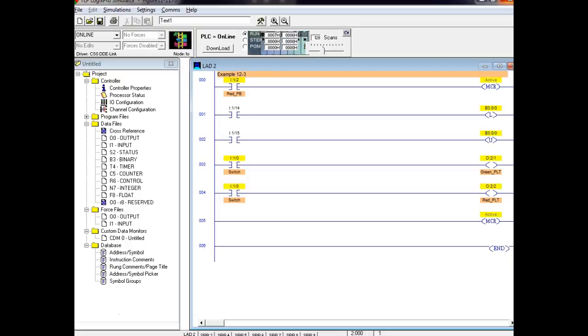If you're by the PLC, you've got power. The 1000 PLCs that y'all are using down there run off 115 volts on the outputs. 24 volts input, 115 volts output. We use PLCs to control these machines over here.